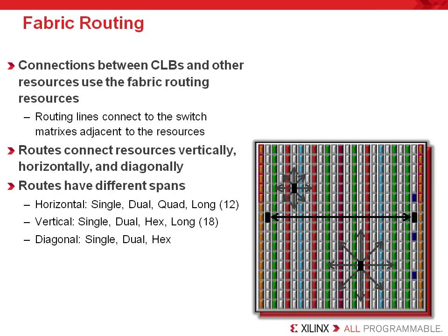The implementation tools select an appropriate routing that may include different kinds of routing resources. The solution that is routed is designed to try and meet your timing needs based on the timing constraints you enter with your design. This will allow the software to choose the most intelligent routing solution to meet your application's timing performance objectives. In fact, the mapping and placement of logical resources is handled by the program called PAR, the Placement and Routing Utility. The routing resources available to your design is fixed and optimized by Xilinx experts.